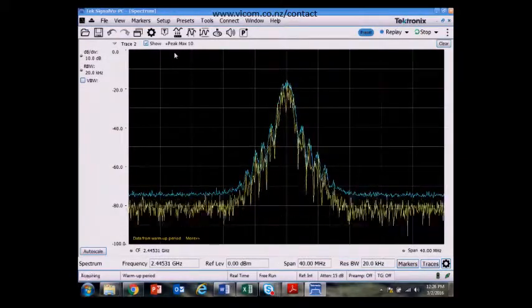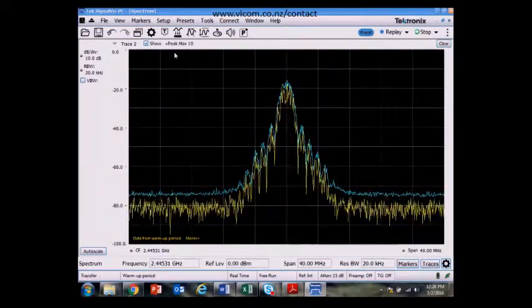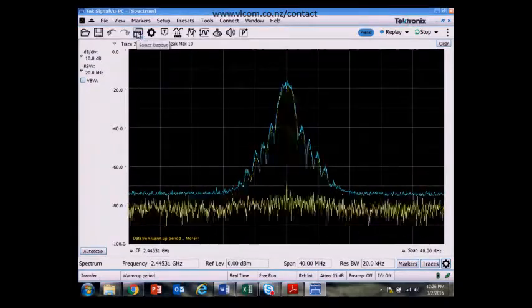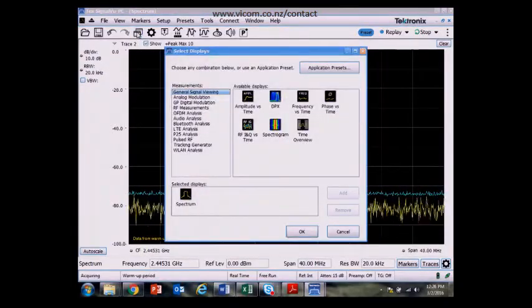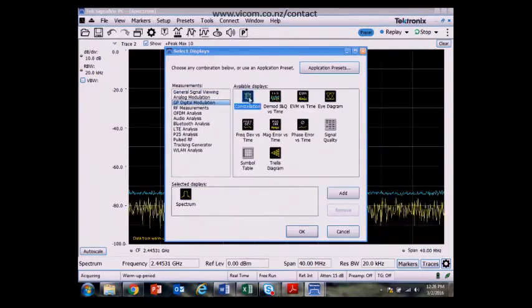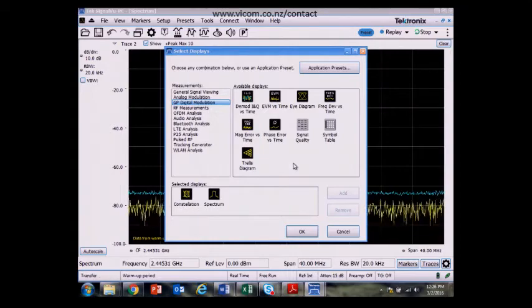So starting out, we're seeing the spectrum display, always a good place to start when doing parametric testing. The way SignalView PC software works is I pull up the selected available displays, and I need to have the option or activate the 30-day free trial for the general purpose digital demodulation. ZigBee uses a type of modulation called OQPSK, or Offset Quadrature Phase Shift Keying, with a half-sine filter.